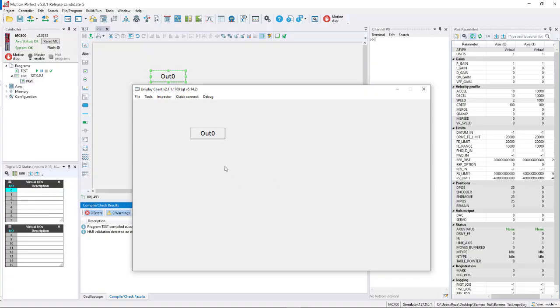If I click again, it will disable the digital output, but it will apply another incremental move on the axis, which moves it to 50 instead, because this is supposed to be an incremental movement. It's deactivated here, but it makes another move command, and you see the move buffer shows the move command. Target is 50 because it adds the 25 increment to the current position, which was 25.